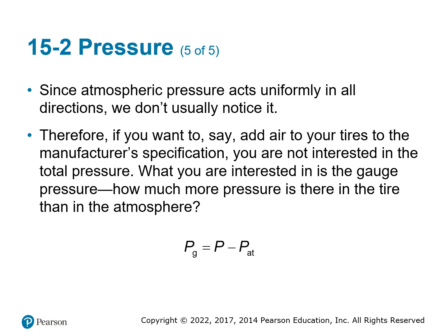So how much more do you need? To get gauge pressure, take the total pressure minus the atmospheric pressure, and that's how much gauge pressure is left. Hence why they call it a tire gauge. It doesn't take into account the atmospheric pressure, but just how much the tire needs.